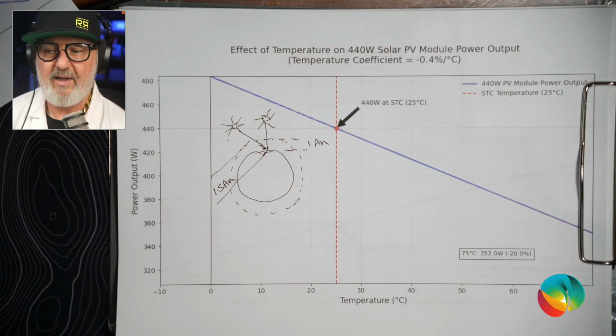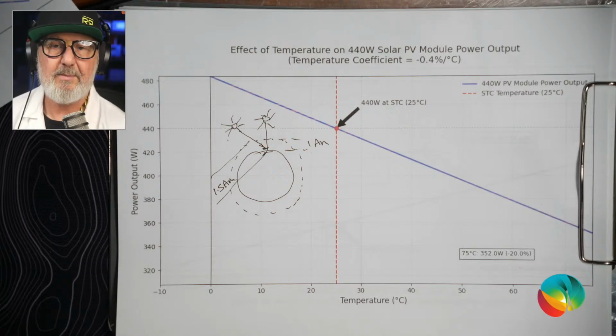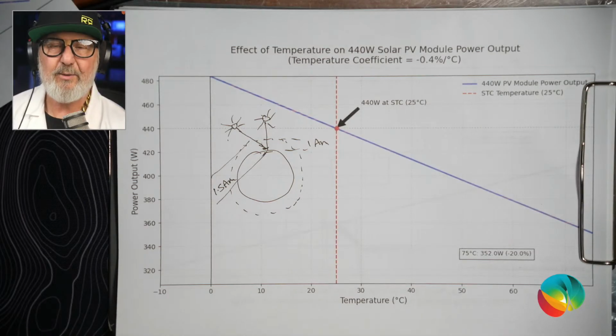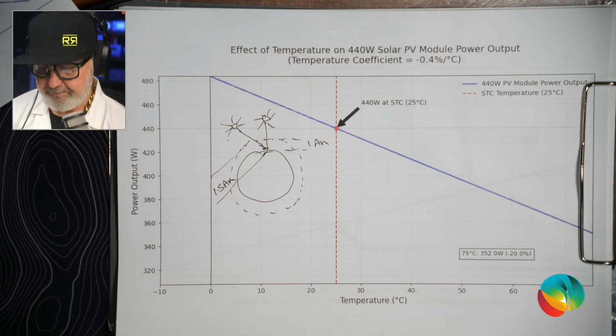So solar panels have a spectrum sensitivity, and depending on the cell types and other manufacturing features, that sensitivity can be biased one way or the other to the short or longer wavelengths. And so for standard test conditions, they go, we'll just choose a typical 45-degree angle sun coming through the atmosphere, and that's what we use for testing solar panels.